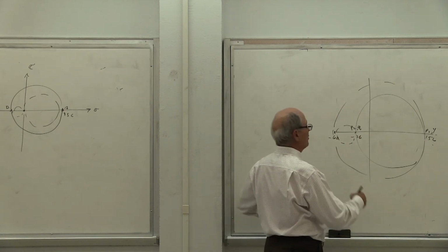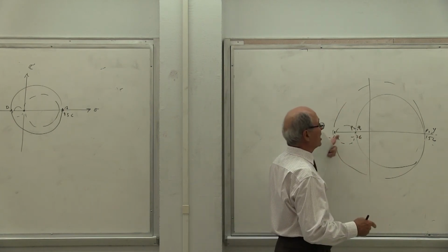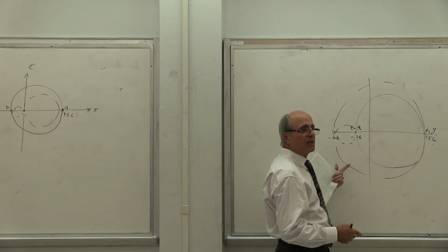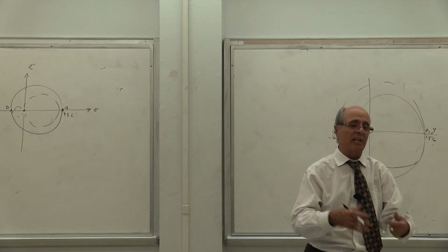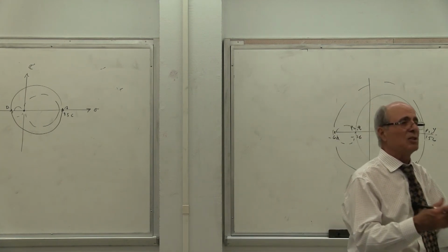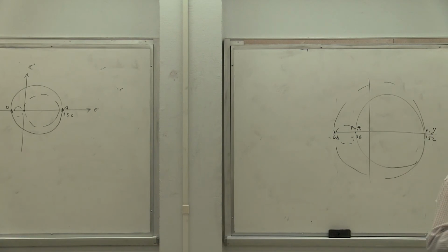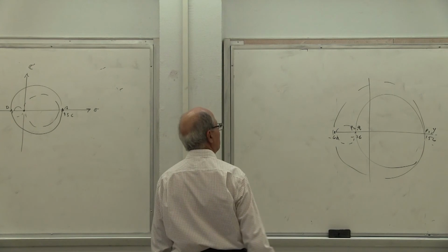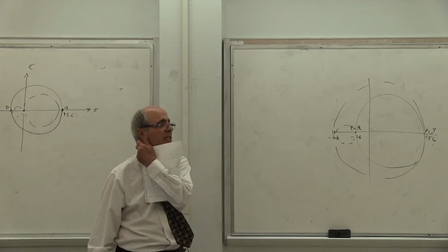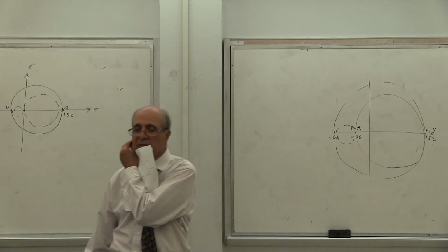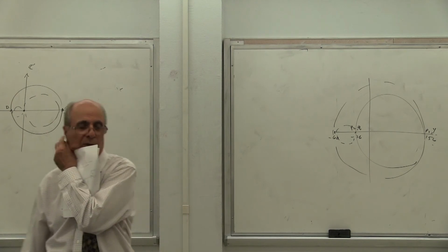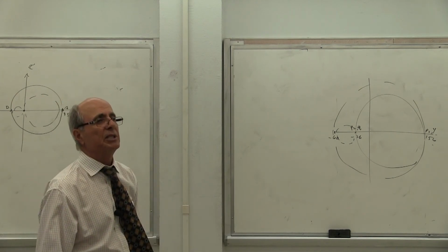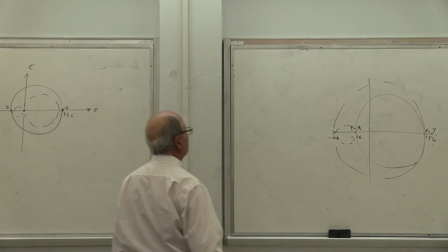But that's not the point. We don't care about that as much. We care about the largest circle because that's what we want for design. And in the design, we don't care whether this tau is positive or negative. You then don't care about it. None of them become important. I'll show you that later on when we go to the shaft design. You will see that positive tau and negative tau will not have any effect in your design criteria. Everybody understand. We'll see that when we go next week.